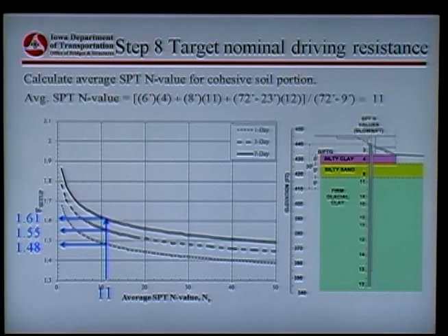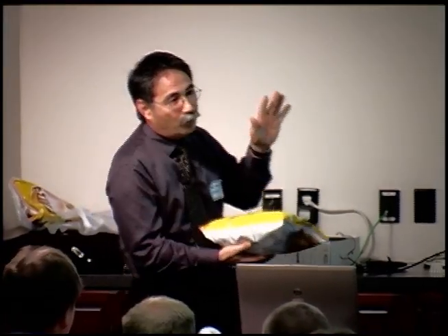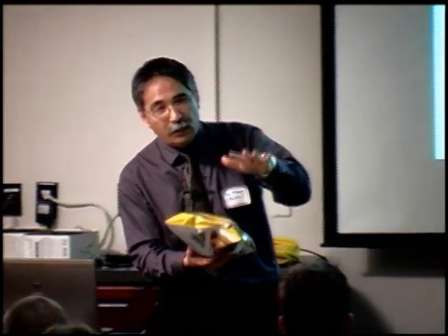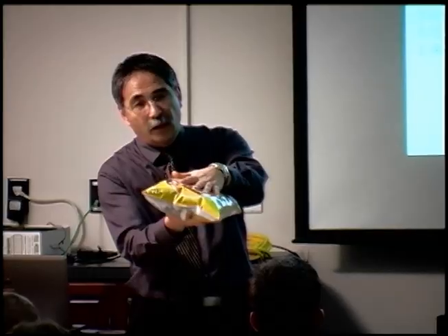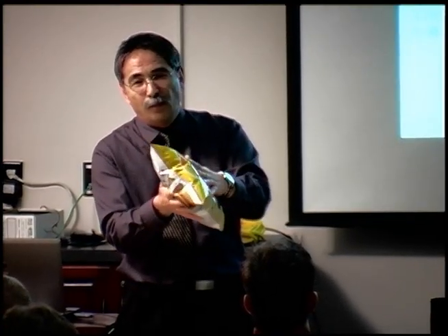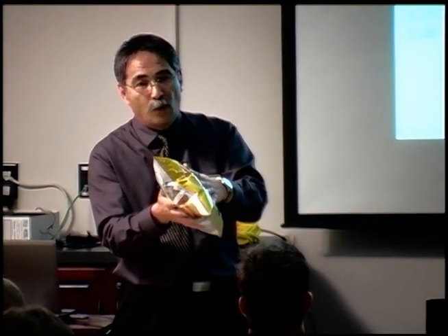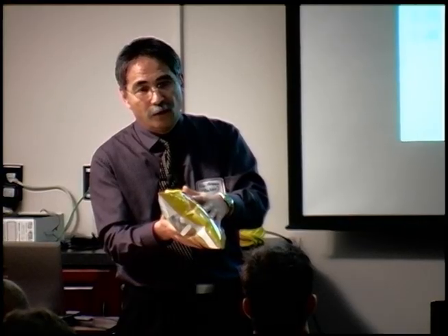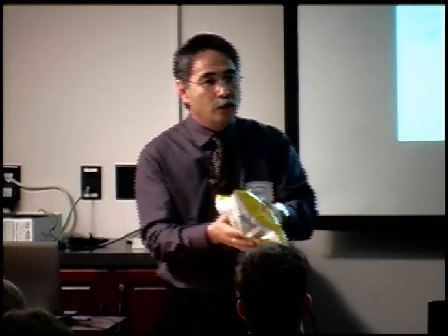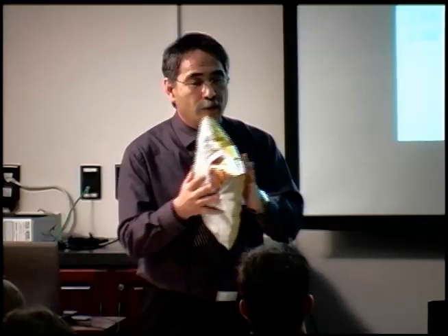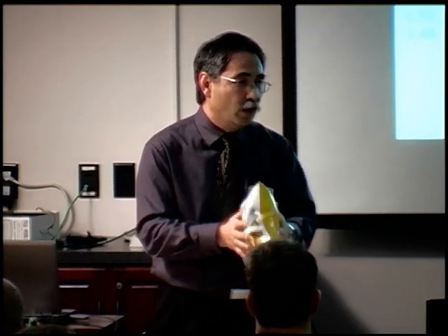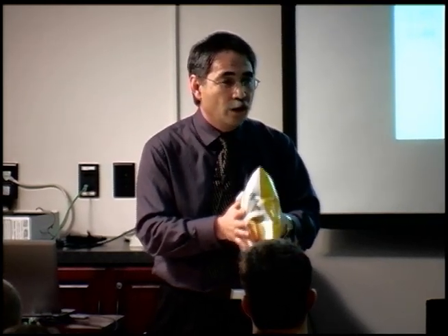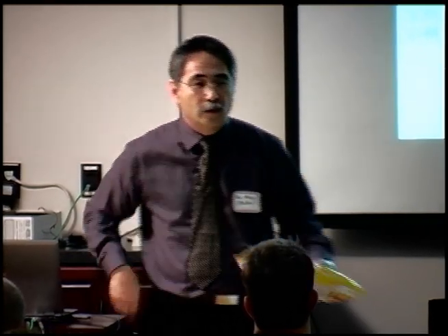So if we had a bag of chips here, and say the pile is driving down, or I load it up with a footing, and so when I press on this, does the volume of the bag change? Or does the shape of the bag change? So all I'm causing the soil to do is to move around, but nothing has physically changed, right? That's a really important concept in soil mechanics overall. Okay, so then where do we get the strength gain?